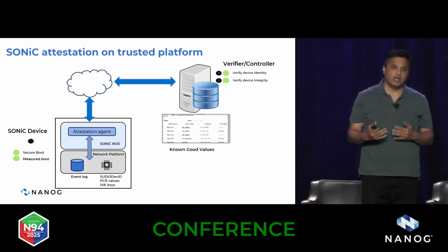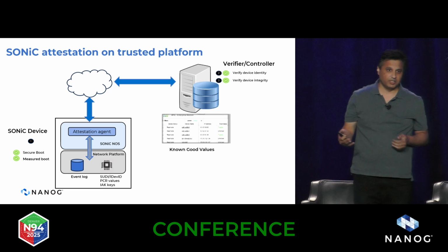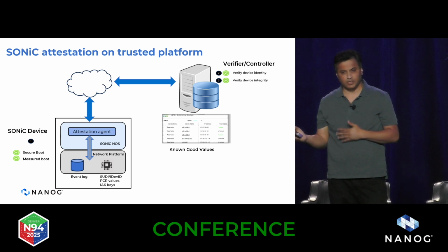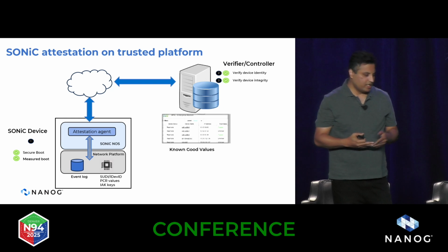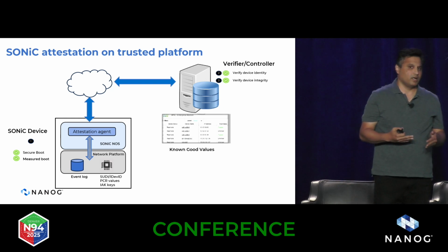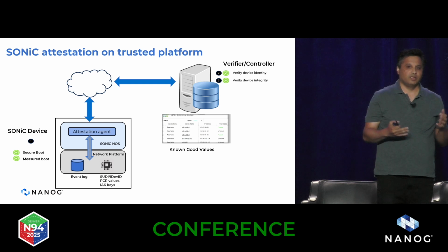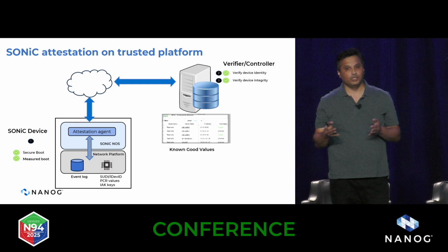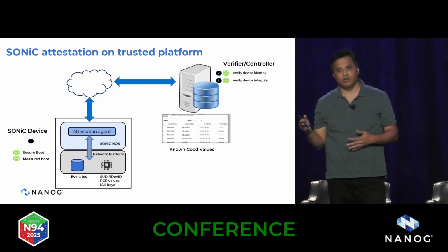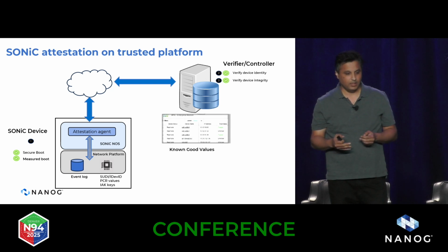Our trust anchor module has a set of predefined registers, which we call Platform Configuration Registers, as per the TCG guideline. There are around 24 registers currently. Each register carries a group of histories. PCR 0 to 7 is typically meant for boot integrity.